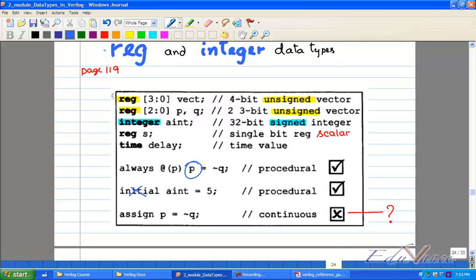Okay. Typically, let me put it this way. I'll rephrase my statement. Reg can be consumed in assign only in a very rare case. Leave that for now. I said yes because I worked on a design where it happens. For all practical cases it cannot consume. Cancel the previous statement's order: in an assign a reg cannot be the consumer. A reg cannot be a consumer.